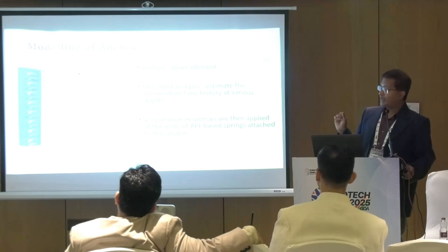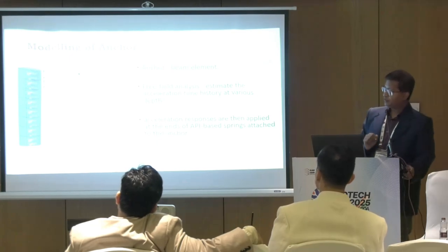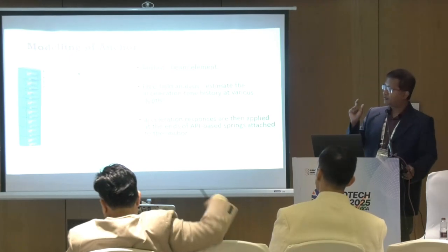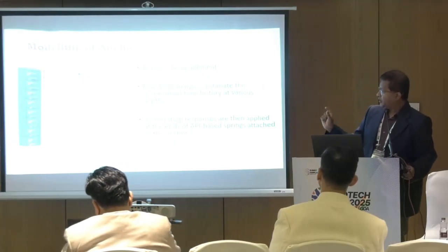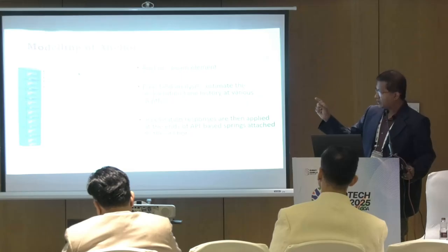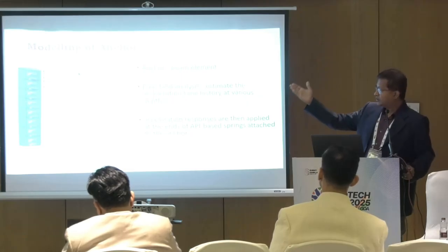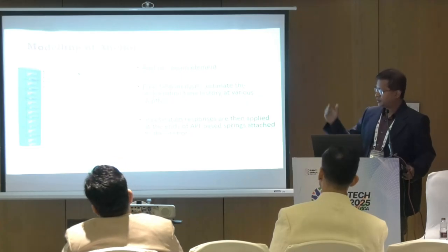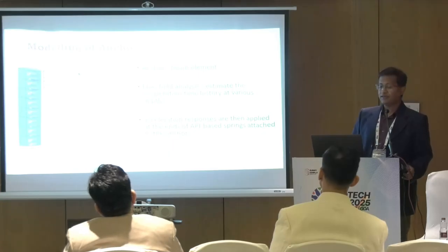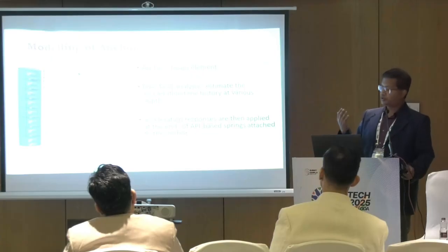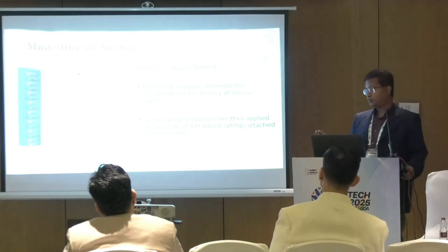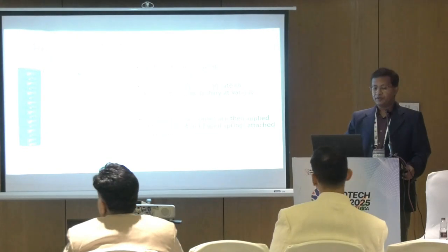Modeling of the anchor is also another important challenge. We can have different types of anchoring systems. This is basically a suction kind of anchor, or a pile kind of anchor, which can also be modeled using a very simple modeling method. Either you can model using a spring-based method like the beam on elastic foundation approach, or a beam on nonlinear Winkler foundation model, or a three-dimensional model.